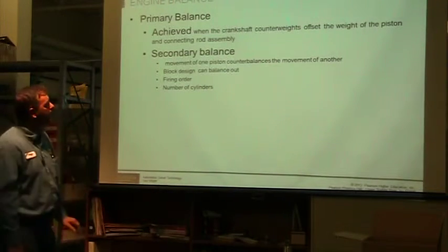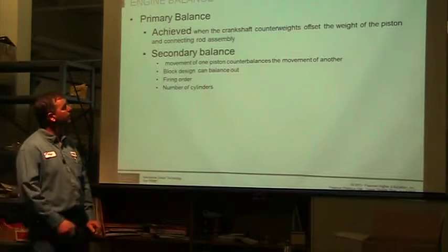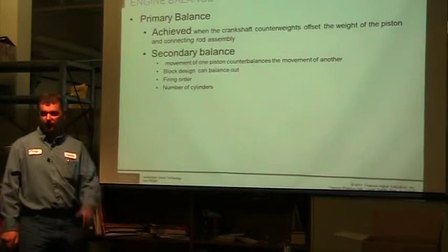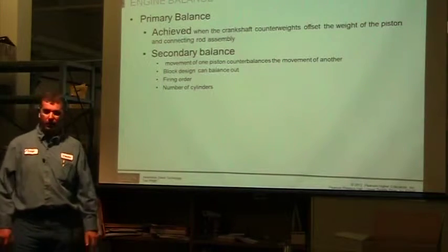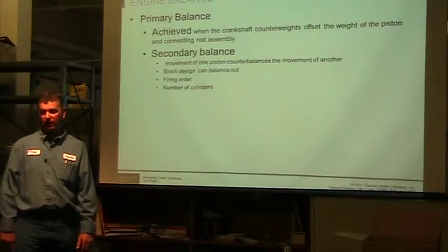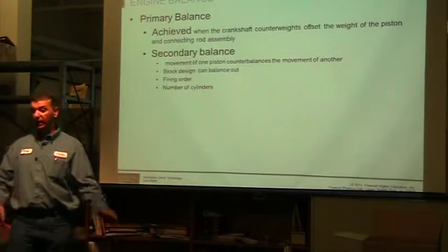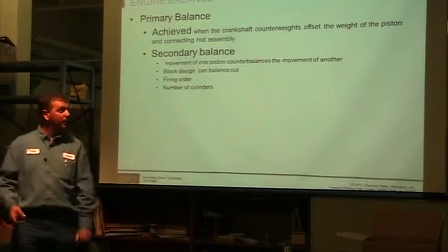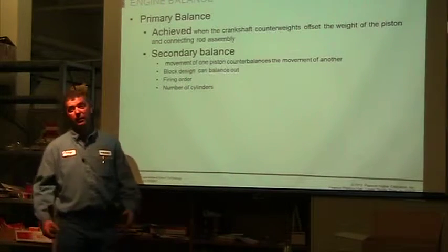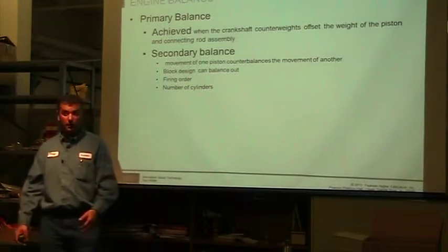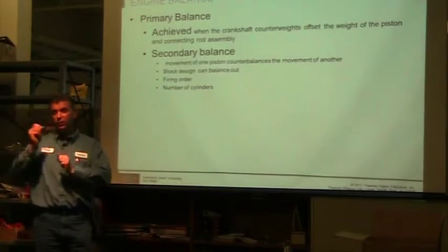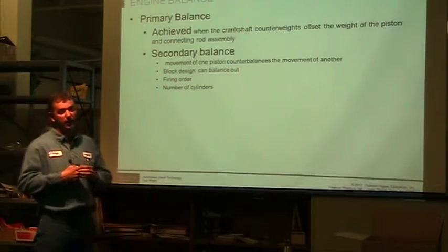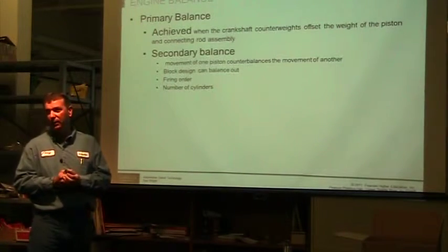Secondary things, there's a lot of different secondary ways. One of them is by having more than one cylinder. A single cylinder diesel engine is going to have some pretty serious counterweights to help counteract that vibration, because you just jerk this thing one way and the other, and it takes a lot. So at least having 2 cylinders helps a little bit, but even a 2-cylinder is rather unbalanced. It's really hard to get a 2-cylinder engine to be smooth without lots of counterweighting.